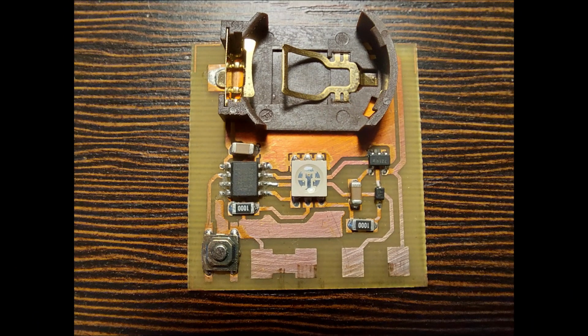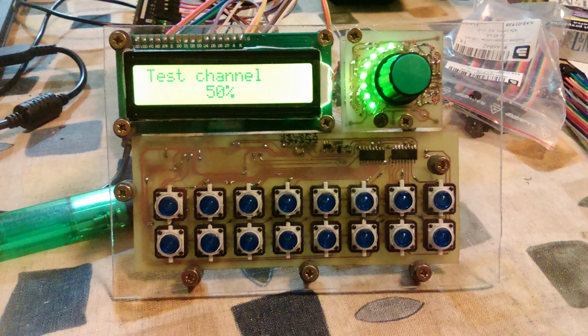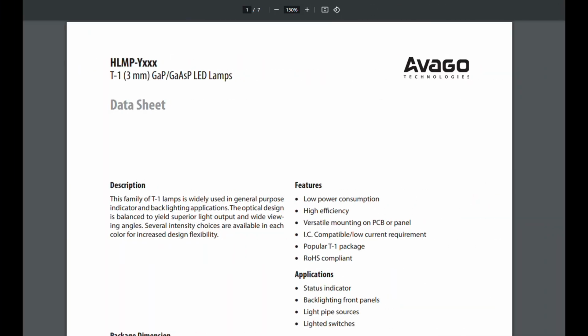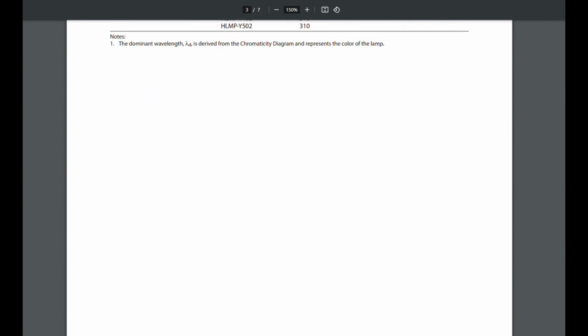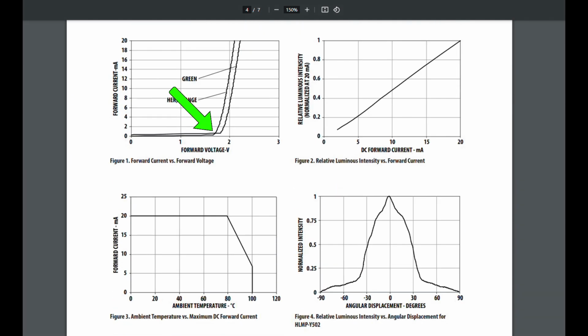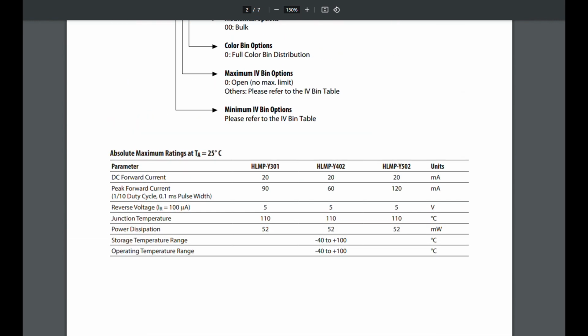But what if you want to use just a single LED? Or make a custom composition of those yourself? As mentioned before, you need to be aware of two things. First of all, LEDs, like all diodes, have some specific voltage on which they start to conduct current. The problem is, this characteristics quickly becomes nearly vertical, so you can't just apply some fixed voltage to it, because it is certain that you will miss desired working point. Instead, you need to limit the current to what is specified as acceptable in datasheet of your LED model.